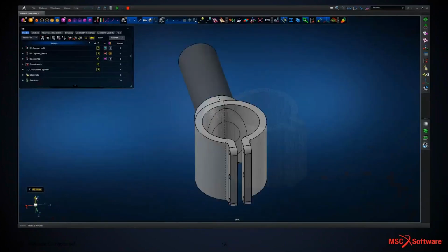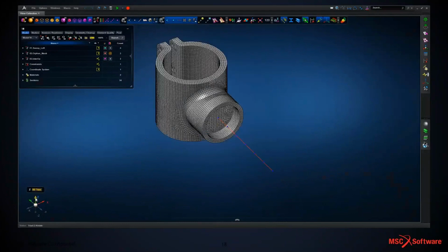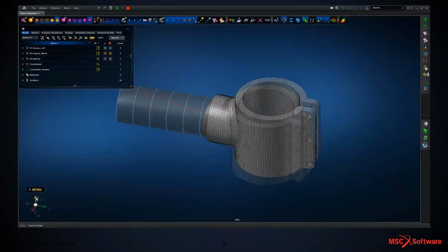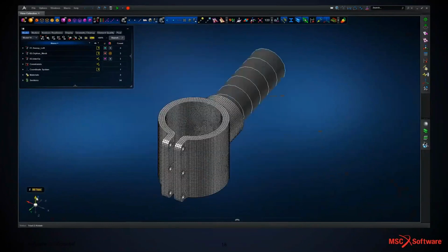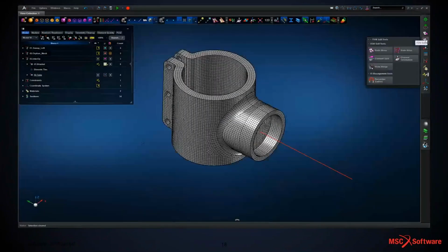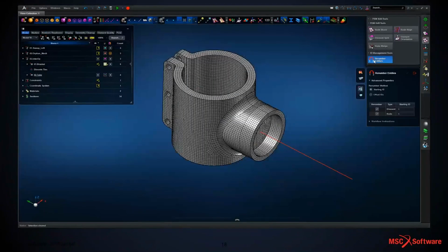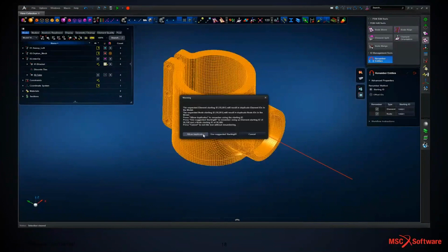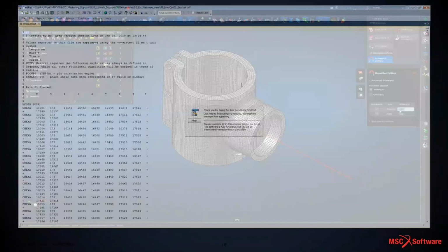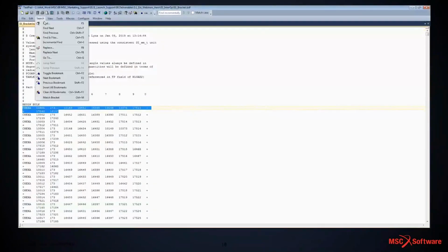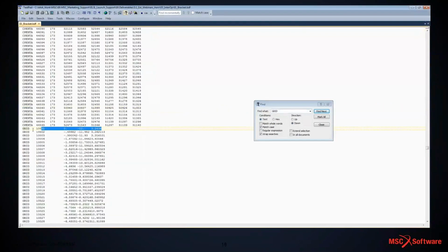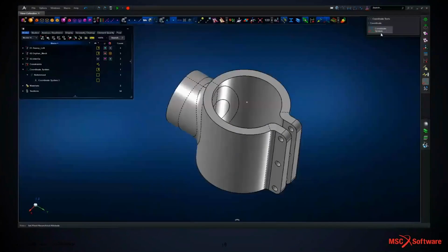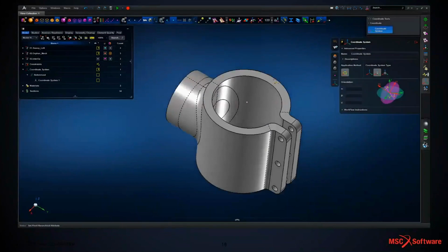So we've got a simple lug and tube definition here. We've got the lug meshed in hex elements, and then the tube meshed in bar elements. We can look at renumbering. So we're going to renumber the elements and nodes from a 10,000 series, again useful for annotating or discriminating result output. So we can look at our resultant deck, and we can see our elements and nodes start at that 10,000 series, so we've got good control over that.